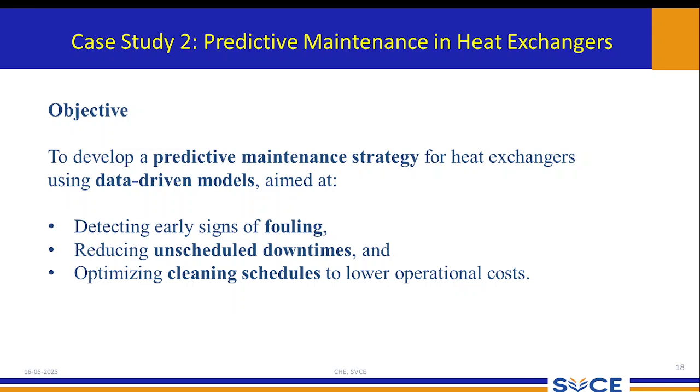Usually the fouling liquid is allowed to pass through the tube side so that the bundles can be removed and we can replace the bundles effectively, rather than letting the fouling fluid pass through the shell side, because the cost is much higher when the fouling occurs on the shell side. So that you are aware of it, that is domain knowledge.